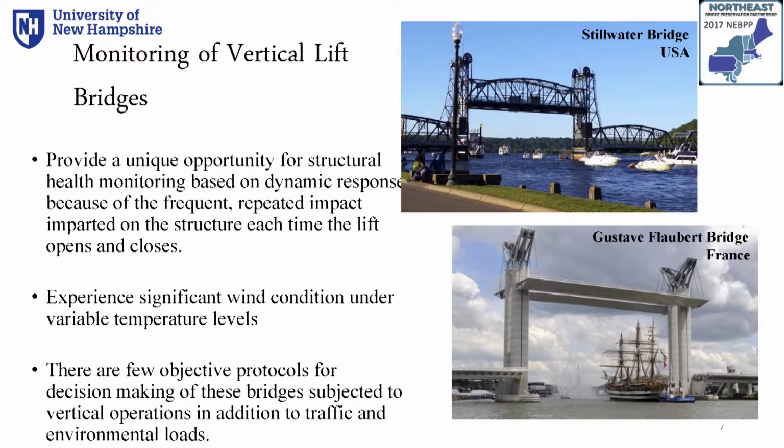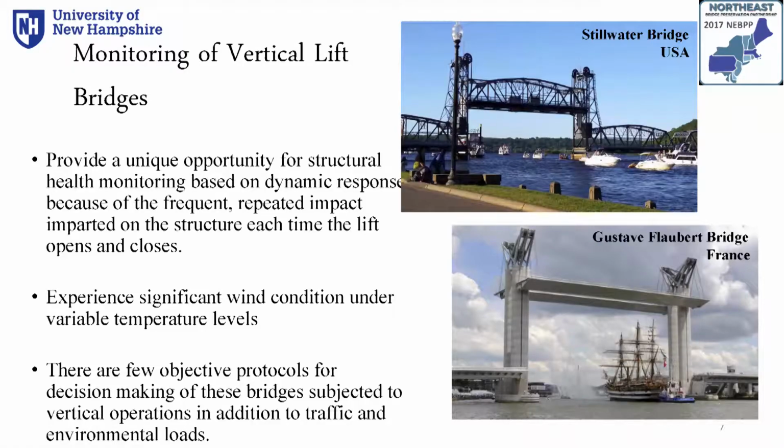Among bridges, vertical lift bridges are very important, and they provide a unique opportunity for engineers involved in structural condition assessments, because they provide a valuable source of excitation that can be used to vibrate the structures and use the ambient excitations to measure the dynamic response of the structures.